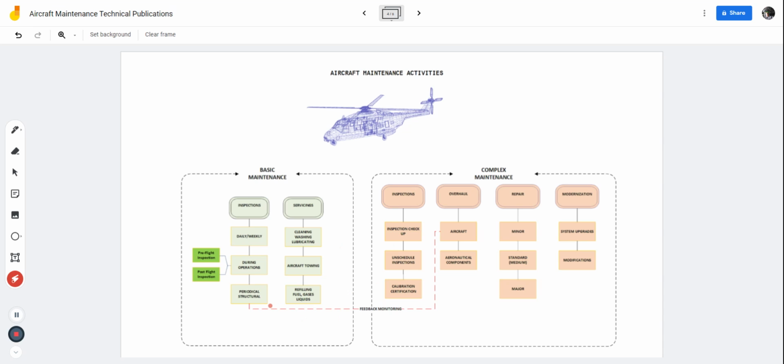And I'm gonna give you the classical example on this slide, on this graph: the normal inspections done in line maintenance also include periodical structural inspections, which is this one here. So those periodical inspections are there for a reason, and it's pretty much for monitoring the structure of the aircraft itself. And like I said in another video, it's not just the monitoring of that aircraft, but the whole fleet. You find something that could be affecting that aircraft, something unusual like a crack or a dent or something in a primary structure of the aircraft.